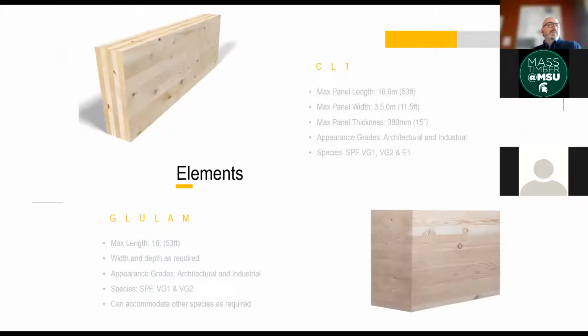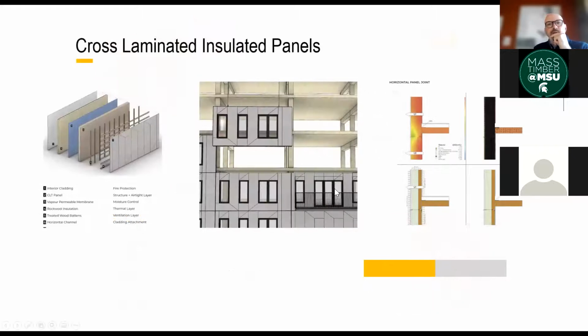They don't put glue on the shorter edge of the lamella where the two panels come together in plane. So what happens is a non-edge glued panel, as it acclimatizes to the environment, will tend to separate on the visible surface of the panel, which makes it a little bit unsightly. Ours reduces the likelihood of separation between the lamella by about 90%. So it's a much nicer, aesthetically pleasing panel than what's typically available here.